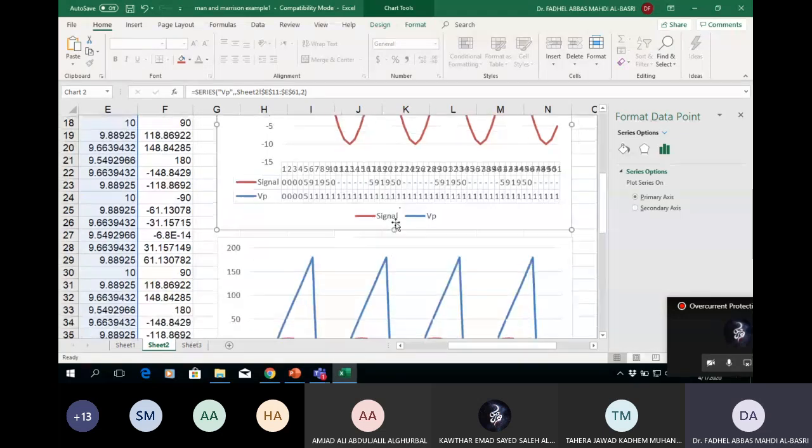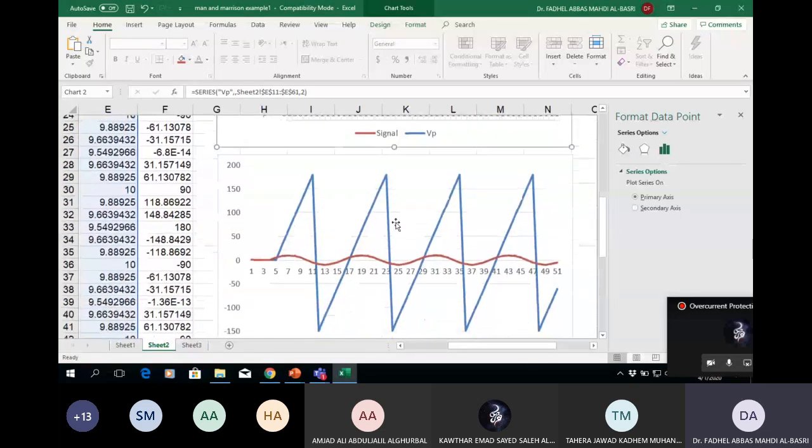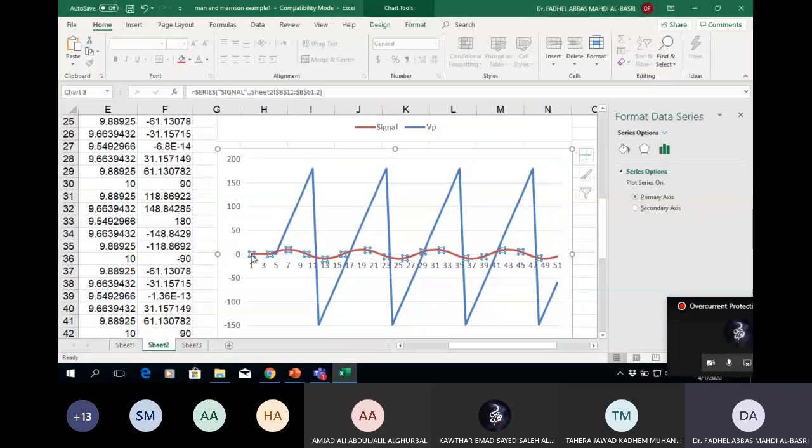Similarly, I estimated the angle of the signal. So the first 3 samples are 0, then one sample comes in, and it estimates the angle. Now what's the angle at peak? It is 90 degrees. So here is the 90 degrees. Now, what's the angle at the zero crossing here? It is 180 degrees.